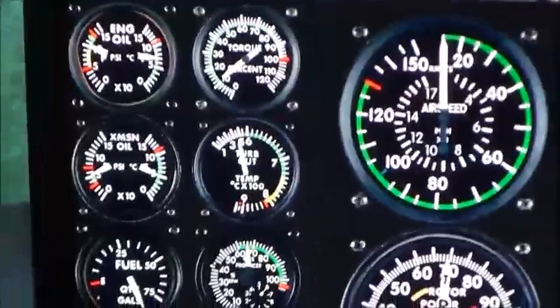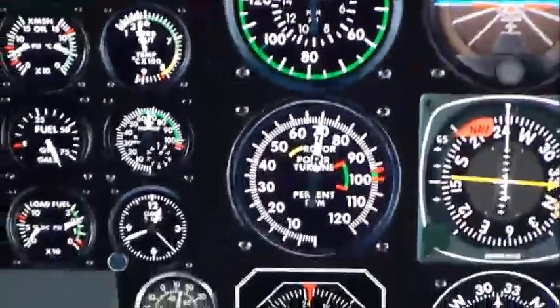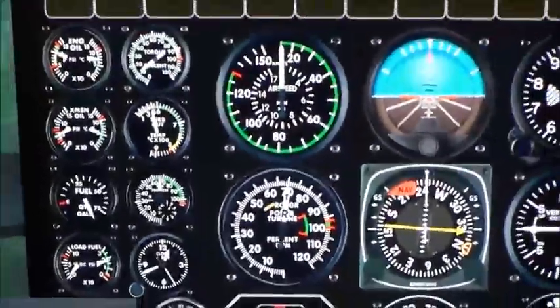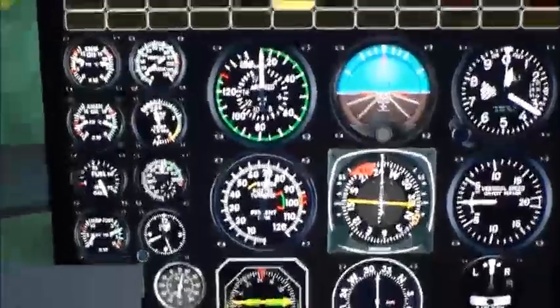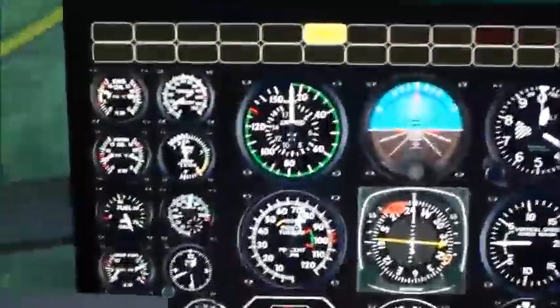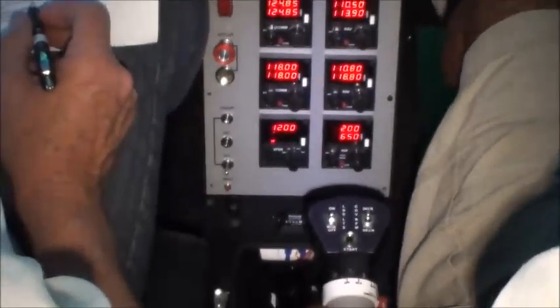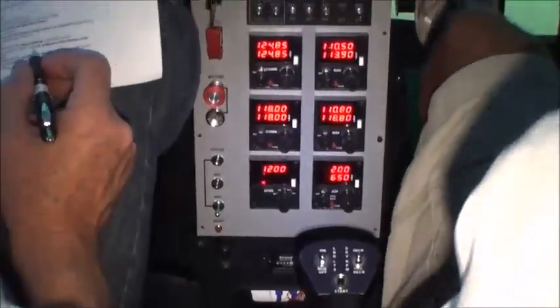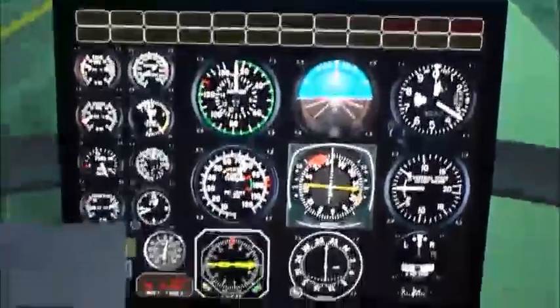Okay. Stabilize engine for 1 minute. We're almost there. Throttle increase to 70%. So 70% in one. Right here. Check. Okay, and generator on. Check. Okay, load there. Collective, cyclic friction on. Friction is off. Check. And throttle increase to 100%.